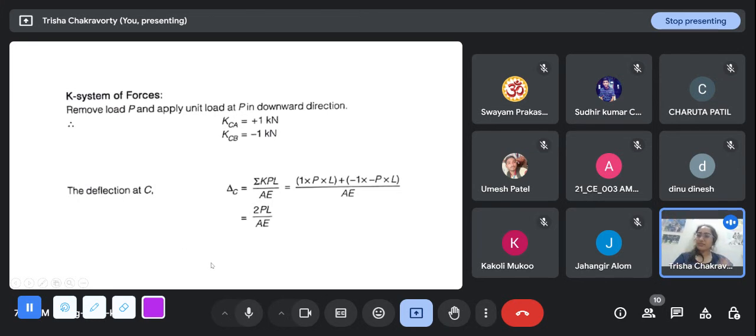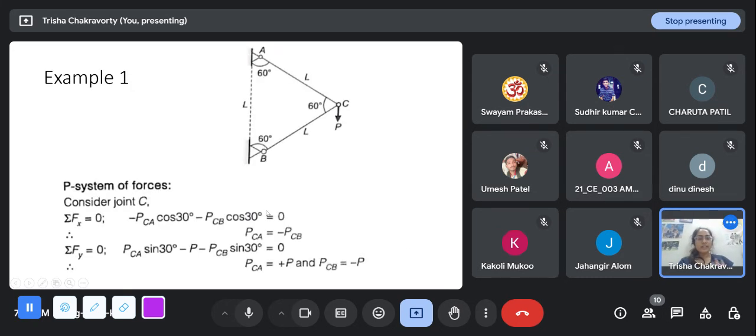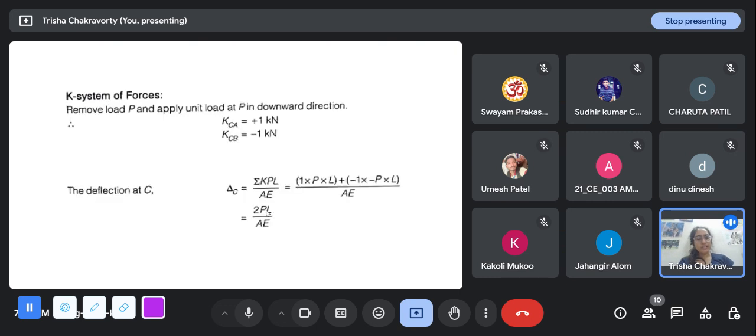And just for the sake of unit, just check once about the unit. P is in kilonewton. Length is meter, so kilonewton meter. And in the denominator we have area, that is meter square, and the Young's modulus is kilonewton per meter square. So yes, the kilonewton crosses out, meter square crosses out, and we are left with a meter, or a millimeter, whatever. When you are actually given numerical values, this was just in algebraic terms, just be careful. Put all these units in a consistent manner.